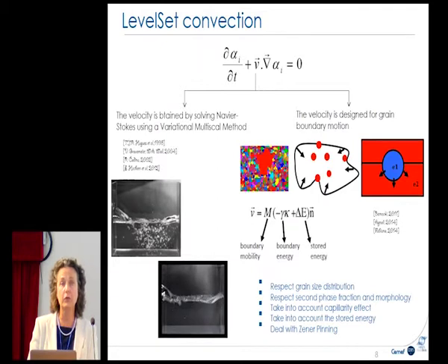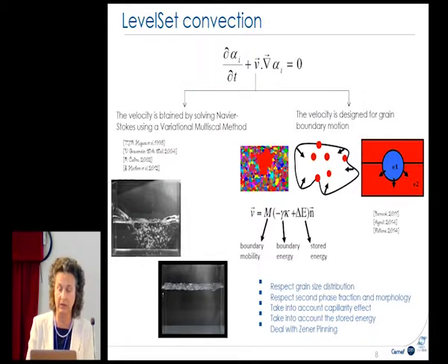So in this case, we use an a priori adaptation. It's an interface description with the metric based only on the geometry and the zero value of the level set function. But we also need to improve the mesh in terms of mechanical computation, in terms of an error estimator in terms of stress, strain, and so on. So in this case, we also compute an a posteriori error estimator. So in fact, we combine the two estimators in order to create this mesh with a gradient at the interface here. So here is the inclusion, here is the matrix, and here the interface.